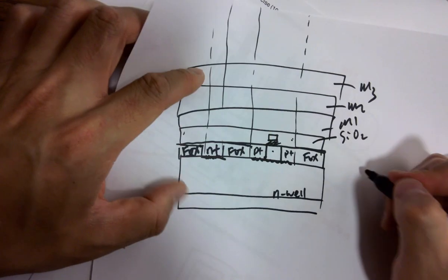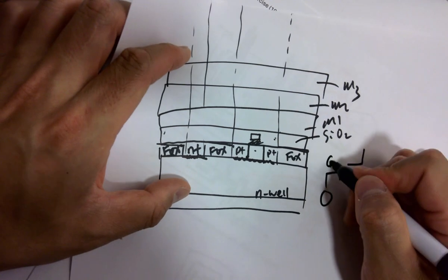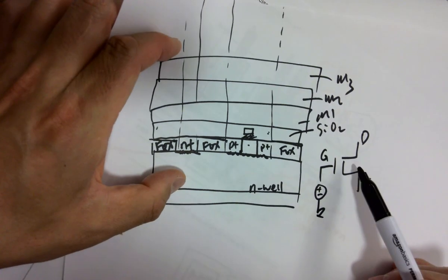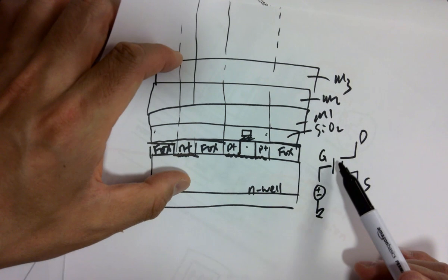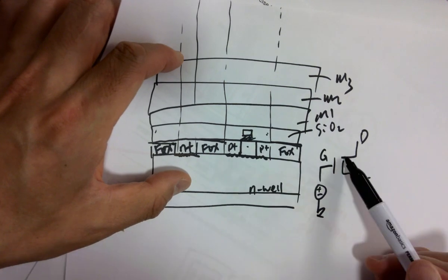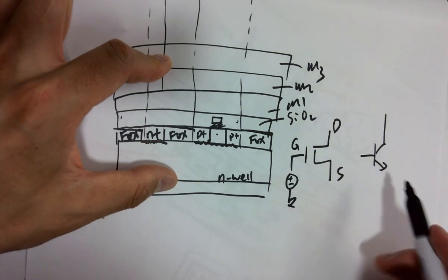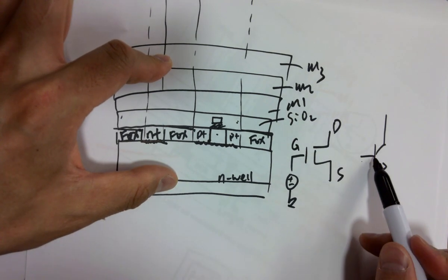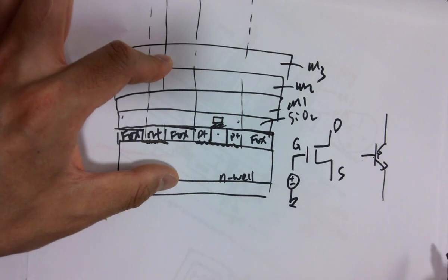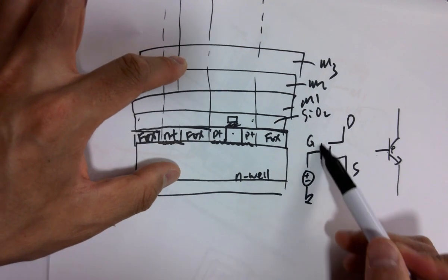So the way to do that is that you connect. You see, this is the gate. This is the drain and the source of the transistor. And from the symbol, you can tell there's a gap. It's exactly the gap I'm talking about. They draw the symbol in the same way. However, for BJT transistors, if you're in analog, is there a gap? No. So the base is directly contacting that NPN, the P junction here. It's making a direct contact. But this one is not making a direct contact, that's why I'm drawing a gap in the middle.